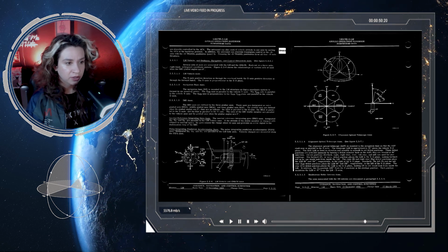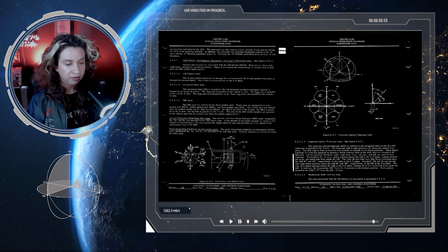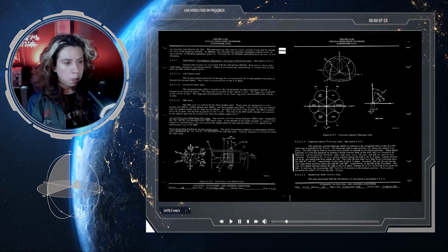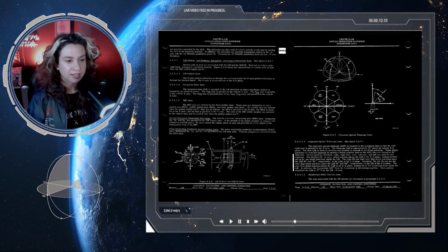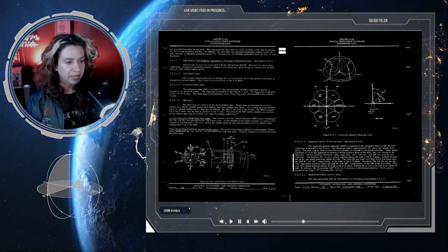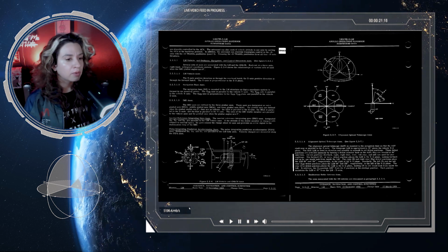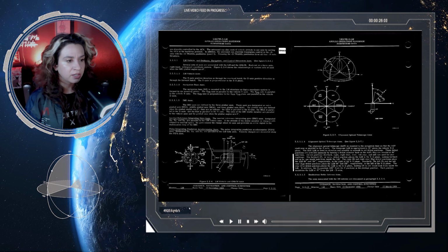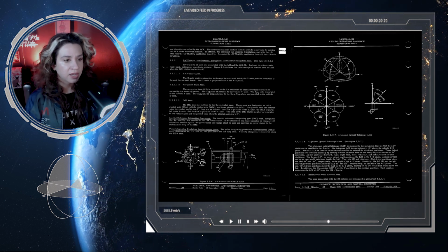The 6 positions, which are forward, right, right rear, left, and left rear, are used for the star sightings. The forward, or F, or 0, detent position places the LOS in the XZ plane, looking forward and up as one would look from inside the LM. The right, or R, and right rear, or RR, detent positions place the LOS 60 degrees and 120 degrees respectively, to the right of the XZ plane.